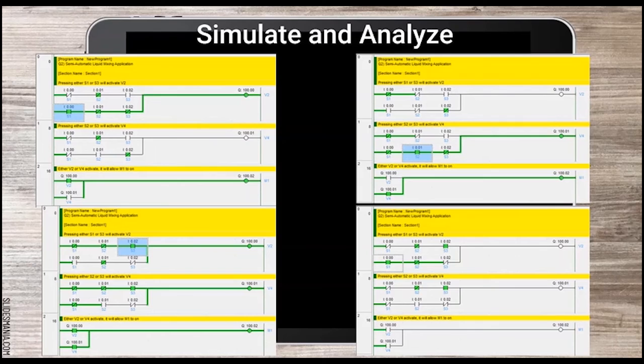Okay, we move to the upper right of this diagram. When switch 2 is triggered at rung 0, due to the interlocking system, switch 2 normally closed contact will open and there is no current flow. But at rung 1, valve 4 opens to refill the tank with liquid 2. And at rung 2, when valve 4 opens, motor 1 will turn on.